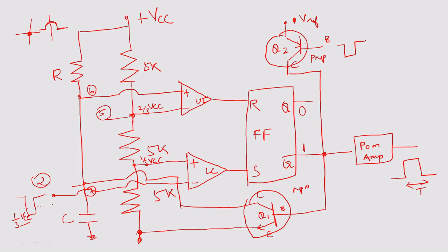You can see here when I am giving 1, this is connected to this Q1. That means the transistor will be on. The transistor will be on and it is connecting this capacitor, right? So that means it is going to the on mode. So that means it is clamping the external timer capacitor to the ground, right?